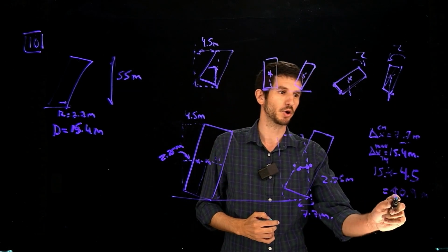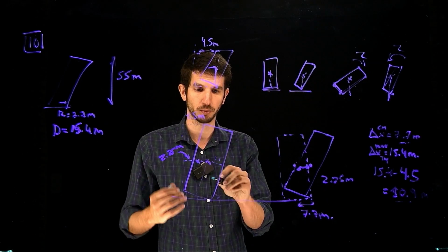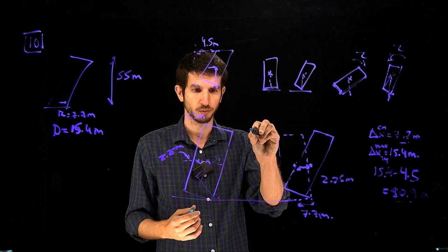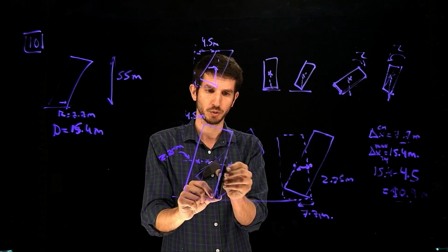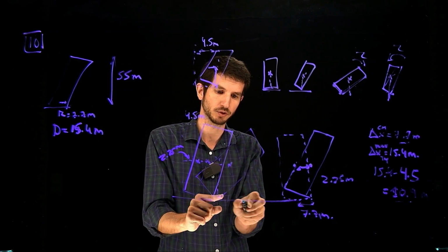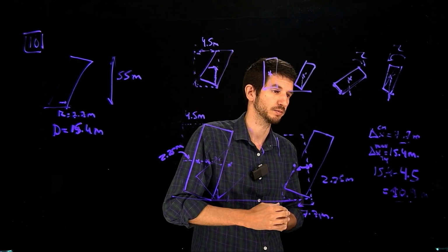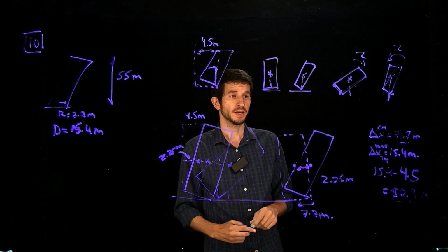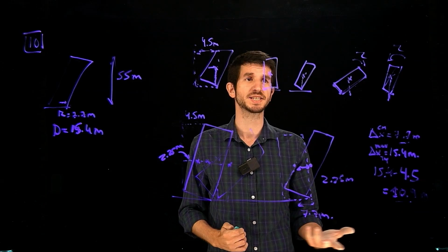The moment it goes farther than 10.9, then what's going to happen is that this thing is going to be completely out of alignment, completely out of here. So the center of mass will be there, let's say, and at that point it's going to start dropping outside, so the equilibrium will be just to tip over, right? And if we see a boat, we will see capsizing or whatever, right? But this is basically the idea.